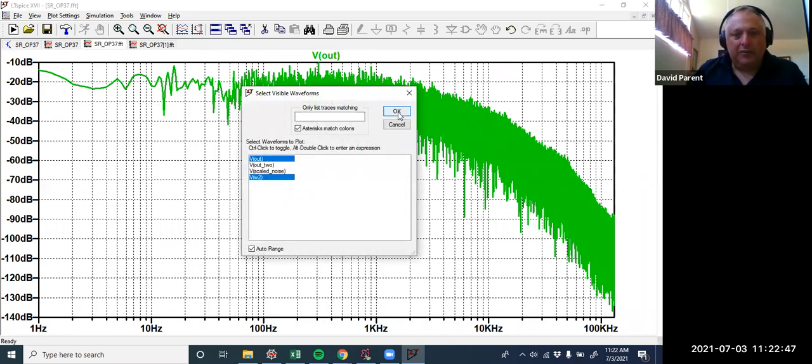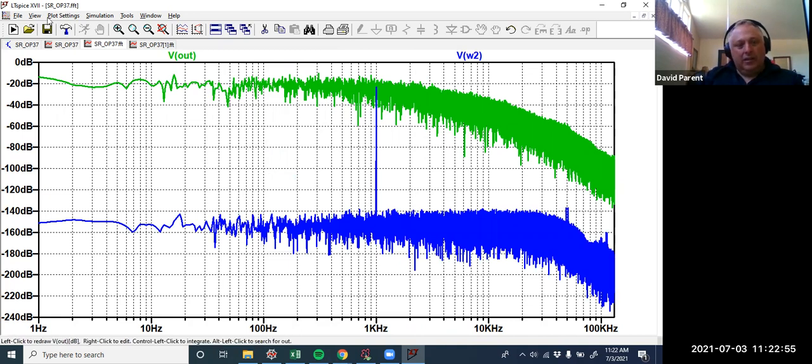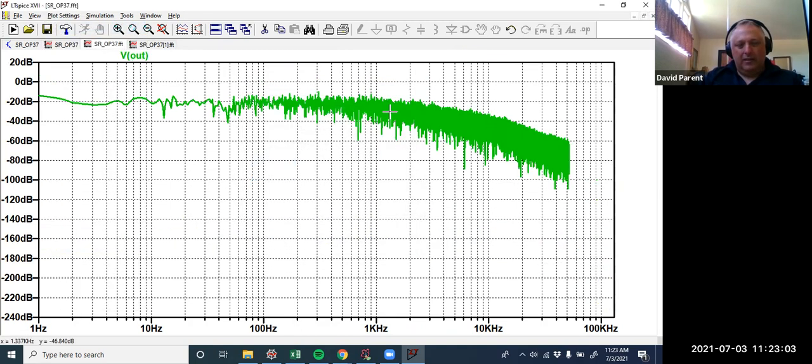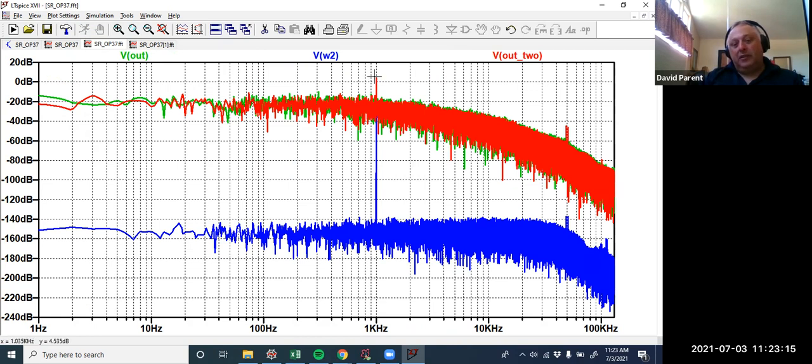Here's our input signal. Okay. And so let's now add the sine wave. Okay. And now here's our output signal. And what we would measure is the ratio of this to this, okay? You might say, but wait, the noise is so low before we put it through the Schmitt trigger, why are we even bothering to do this? Well, this is just a pure simulation environment. This would be a more real environment where noise already exists, all right?